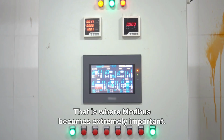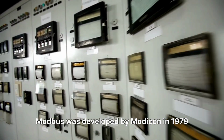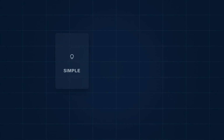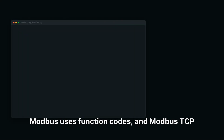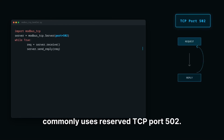That is where Modbus becomes extremely important. Modbus was developed by Modicon in 1979 for process data exchange. It was designed as an application layer protocol and can be used over serial and Ethernet systems. This is the beauty of Modbus. It is simple, open, and easy to implement. That is why it is still used in utilities, water plants, energy systems, and SCADA networks. Modbus uses function codes, and Modbus TCP commonly uses reserved TCP port 502.